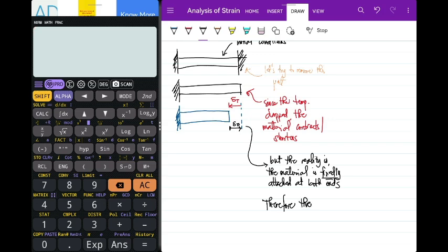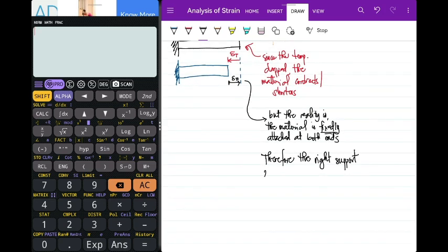It's because the rigid wall at the right side exerts an internal force equivalent to the thermal stress exerted by the material, to maintain equilibrium, so that the wall will not move.